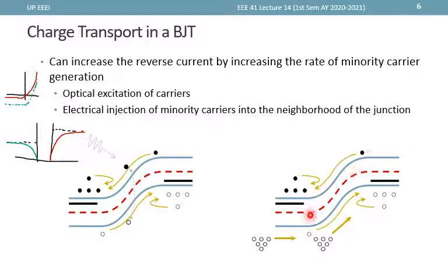And since this one is reverse biased, changing the voltage here does not change the current much. We can control the current by controlling the amount of injected carriers. And so this allows us to operate the output of the BJT like a current source by controlling only the amount of carriers injected. Regardless of the voltage at this portion, we get the same amount of current.